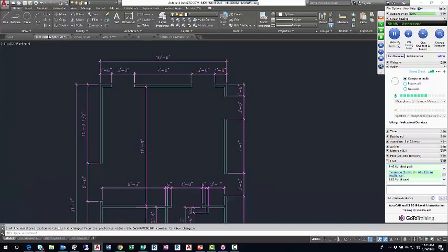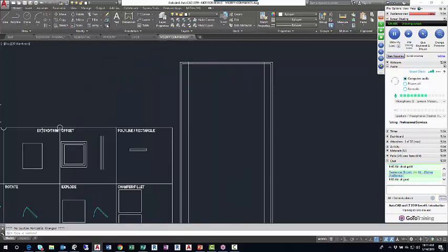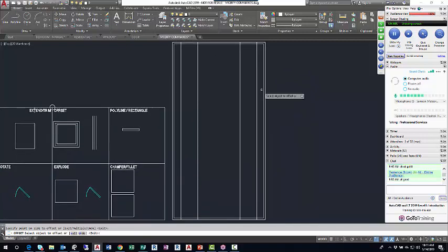Then we saw that the windows were 3 feet wide, so my next offset distance is 3 feet. So I'll go offset, didn't quite start it, offset, there we go. Move the crosshairs into the drawing window, 3 feet, enter. I'll left click the new line I made, move right, left click. Come over and left click the other line, move left, left click. So there's the result there.